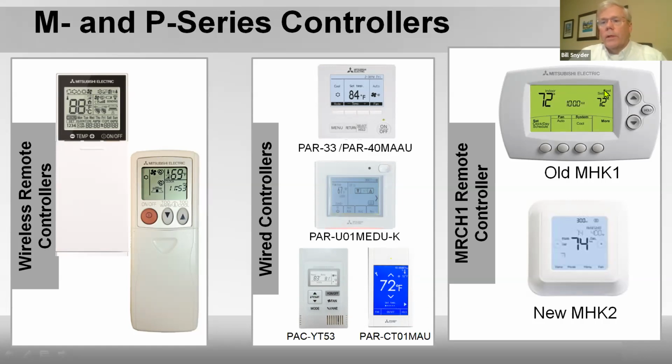And then over here, this is the old MHK1 that is being replaced by this MHK2, which Mitsubishi is just about out of these now, and once they're out, they will start to ship this one. And once we're out, we will start to ship this one. So it's this MHK2 will replace this. This is a RedLINK type controller that's wireless. There's a little receiver that mounts up at the indoor unit, and this mounts on the wall.